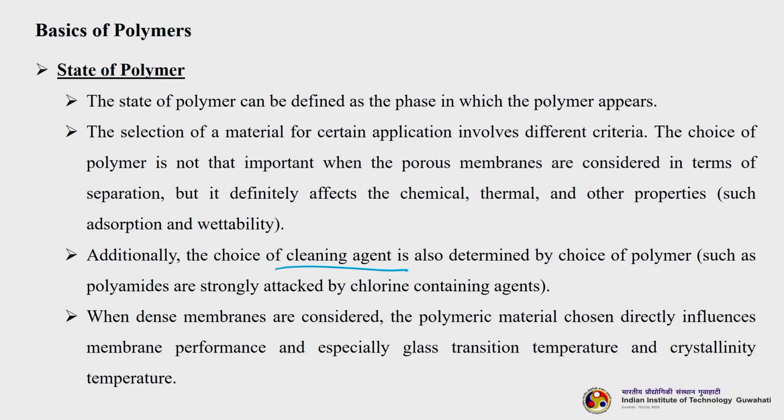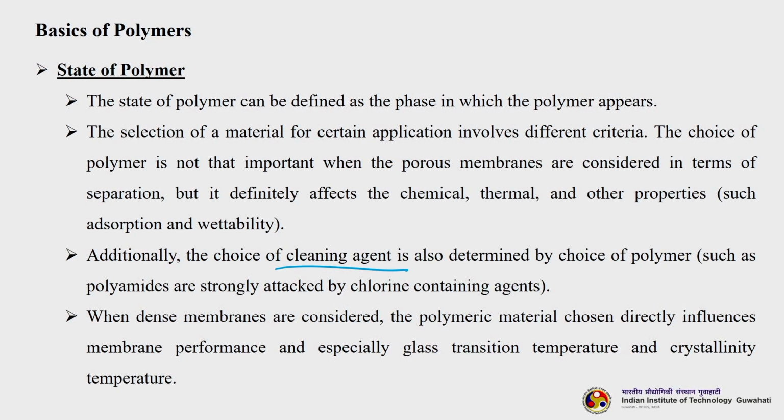So, the pores will get cleaned, but many times the pores are not cleaned due to strong interaction of the solute molecules with the membrane material. So, you need to use some organic solvents, dilute acids, some alkalis or other solvents to clean it. This type of solvent may swell the membrane material. That is why the choice of polymer also governs the choice of cleaning agent. When dense membranes are considered, the polymeric material chosen directly influences the membrane performance, especially the glass transition temperature and crystallinity, especially when there are no pores, in non-porous membranes.